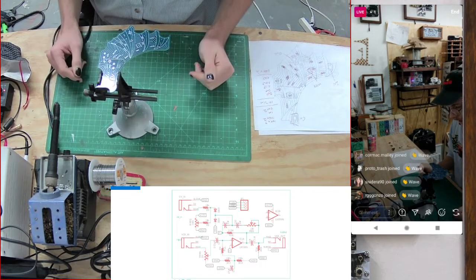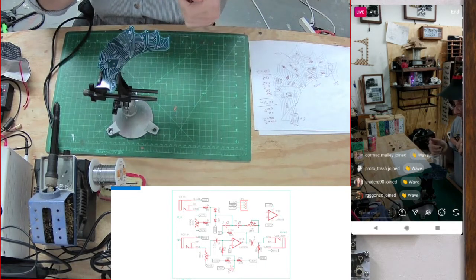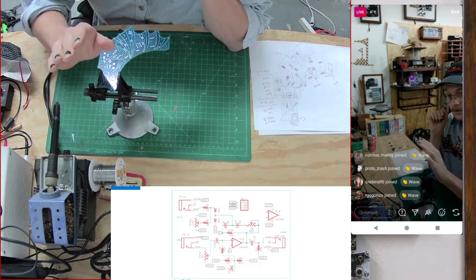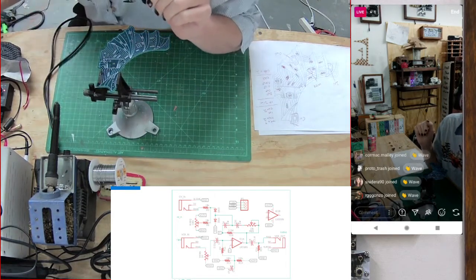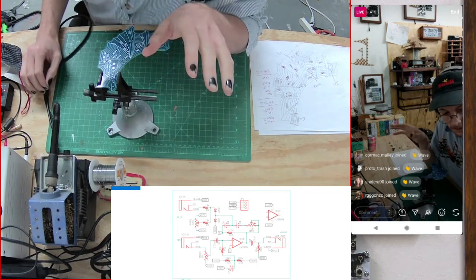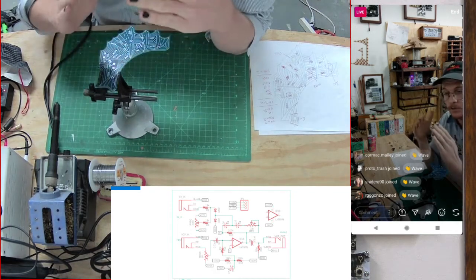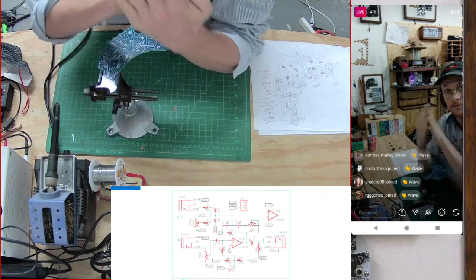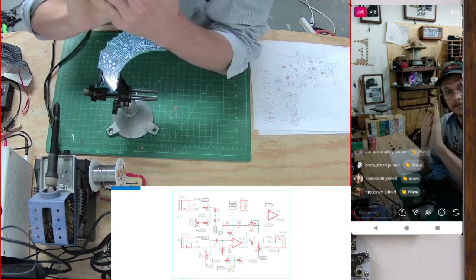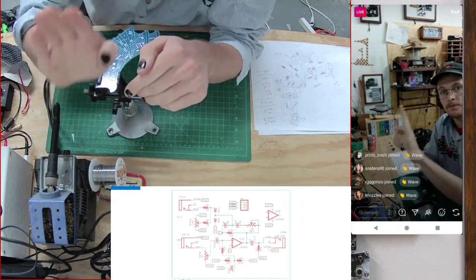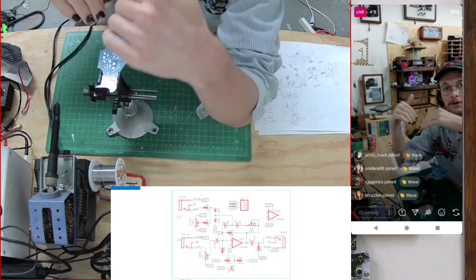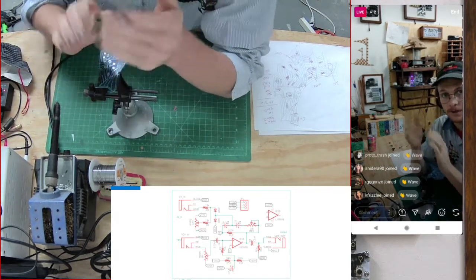If you think of a graph, low pass lets only the low frequencies through. High pass lets only the high frequencies through. Band pass will only allow a select band of frequencies through, like a little bump that can be moved back and forth. And notch is the inverse of that, so all frequencies except for a small range.